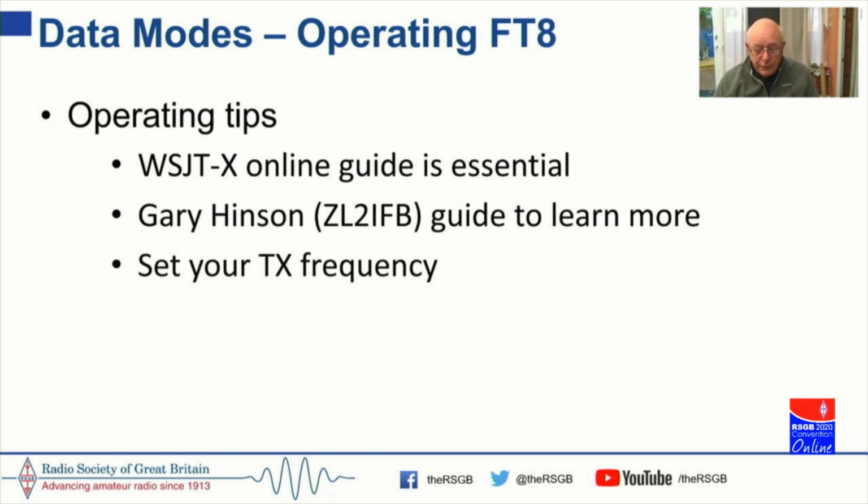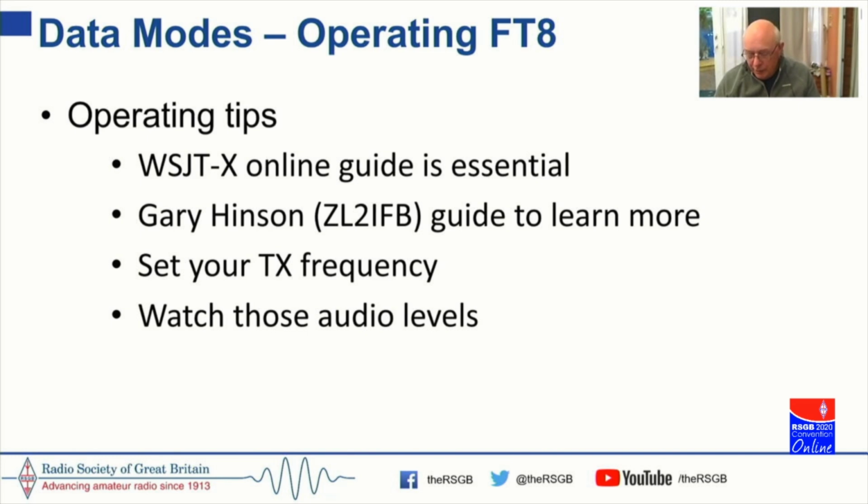So remember, set your TX, your transmit frequency, on a free slot using the wide graph, because that'll improve your chances of success. And do be careful of the audio levels, because if you overdrive the audio, the distorted audio signal that results will go into your SSB transceiver, and all those distortion products will be broadcast, and it comes out as a real mess. So it's just one thing you need to be careful of in particular.